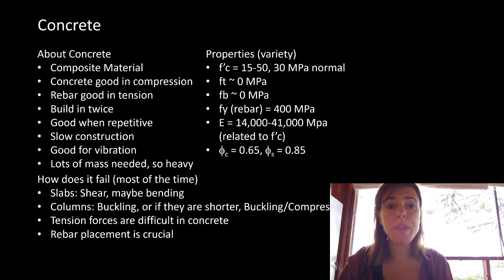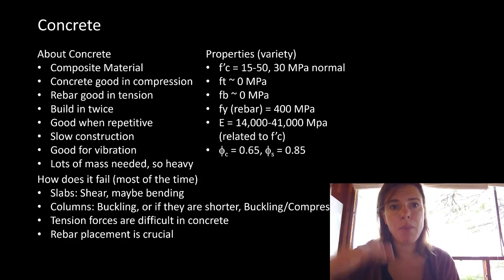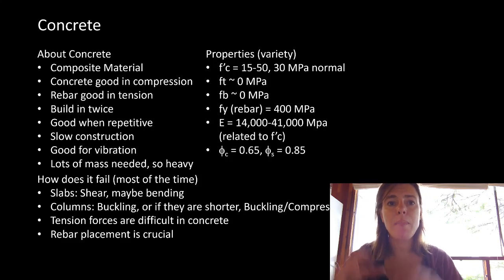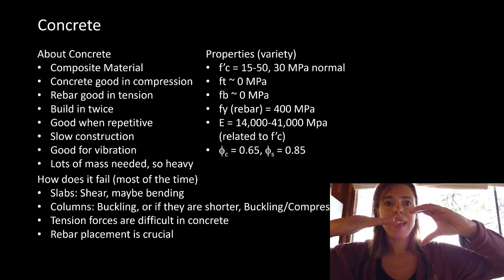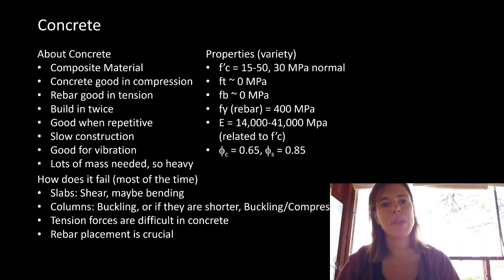But because of this, rebar placement in concrete is critical. Making sure it's in the right spot and that it's where it needs to be is the most important thing. It's funny because the labor force doesn't have to be highly trained in rebar placement. If they don't understand the critical factor of that rebar, it's very easy to make a mistake. I'm not saying that's always what happens, but for the people installing it, it's not always intuitive that it would be such a big problem. The rebar's in there, what does it matter? Making sure it's not in the middle and down at the bottom, you wouldn't think would have that big of an impact, but if we're talking about something being in bending, having the steel in the middle is going to be less effective than being down at the bottom.